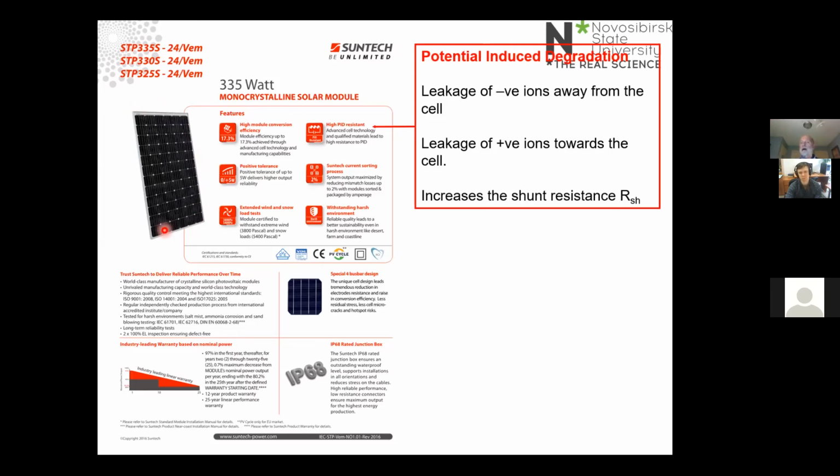Now, this is done for about a millisecond, because PV has no inertia. You don't have to illuminate a module for very long before you can measure the power output. So that flash test is used by all the good manufacturers of PV modules to test every module that they manufacture. For this module, they do the flash test, and then they decide which of these categories the newly made module fits into. So if the flash test says it's 327 watts output, then it will be classified as a 325 watt module.